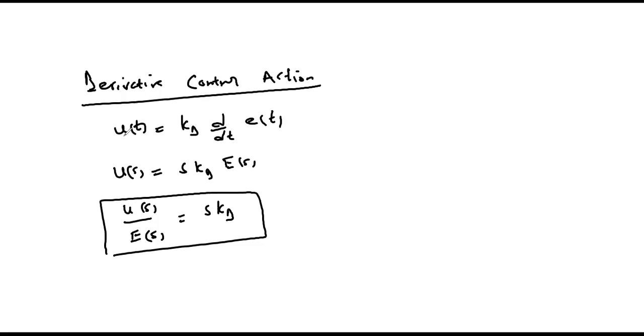And that means that the derivative control law provides a large corrective action in anticipation, even before the error gets large. This is the main advantage of the derivative control action. It has an anticipatory corrective mechanism on its own.